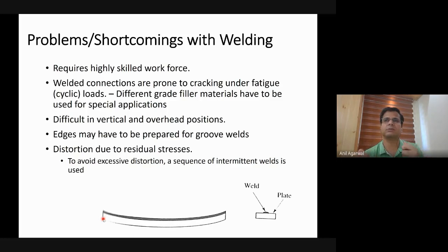Otherwise, these distortions can be so bad that by the time you are done with almost all the welding, by the time you reach the last parts to be welded, they will not fit at all. The components will be so badly distorted that the last parts will not fit. Okay. So this is something that one must be very careful about. That is usually not a problem with bolted connections.